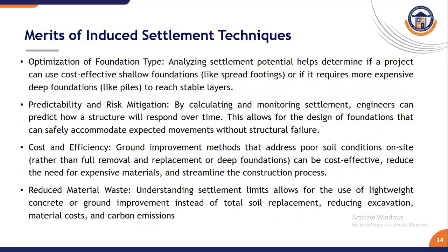Finally, the merits of induced settlement techniques. Here various benefits are there: optimization of foundation type by using the settlement techniques, predictability, and risk mitigation. Cost and efficiency of the building will be improved, reducing material waste. Understanding the settlement limit allows the use of lightweight concrete or ground improvement instead of total soil replacement, reducing excavation, material cost and carbon emissions.